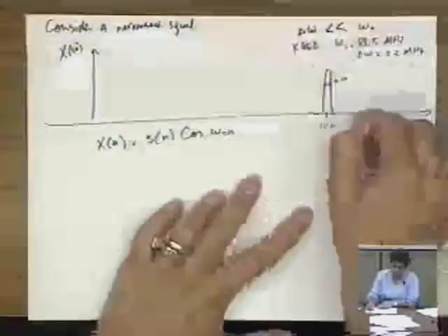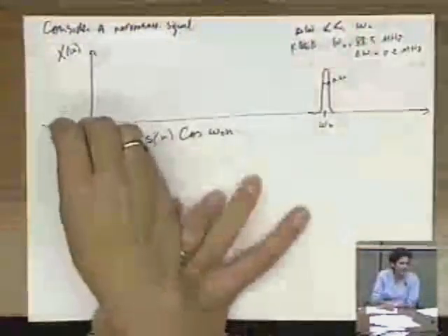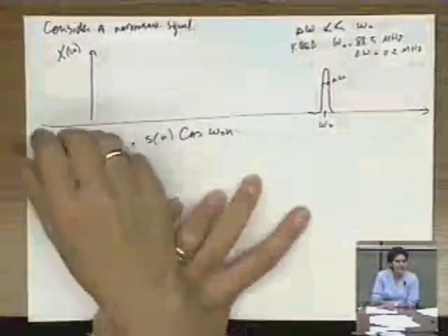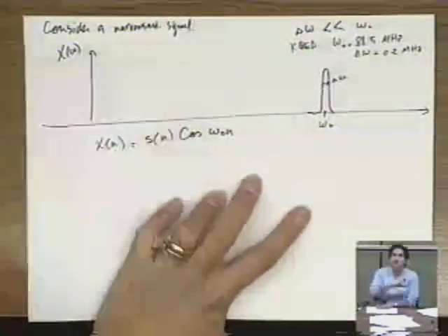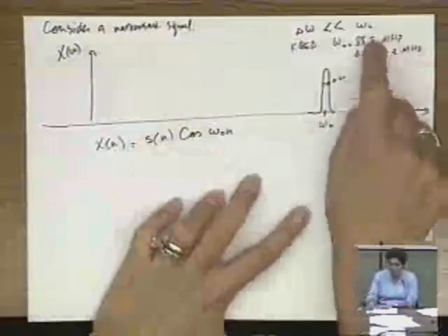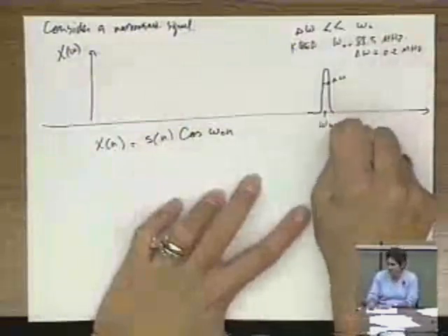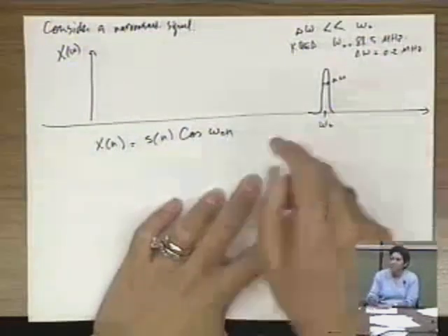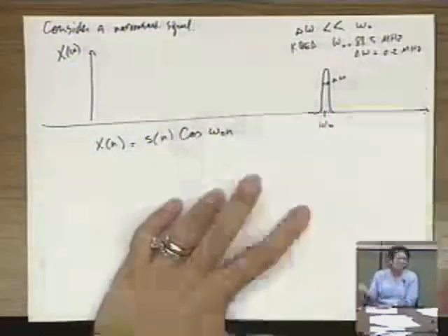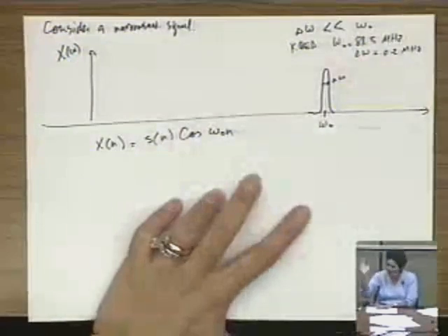Okay. By the way, one of the trends in radio signal processing is that previously when you designed radios, you received the signal, you had a filter, and first you demodulated it, you brought it to baseband, and then you A to D sampled it. And now one of the trends is the A to D technology has improved so much that you can even sample this at twice the 88.5 megahertz, at 170 megahertz, for example.